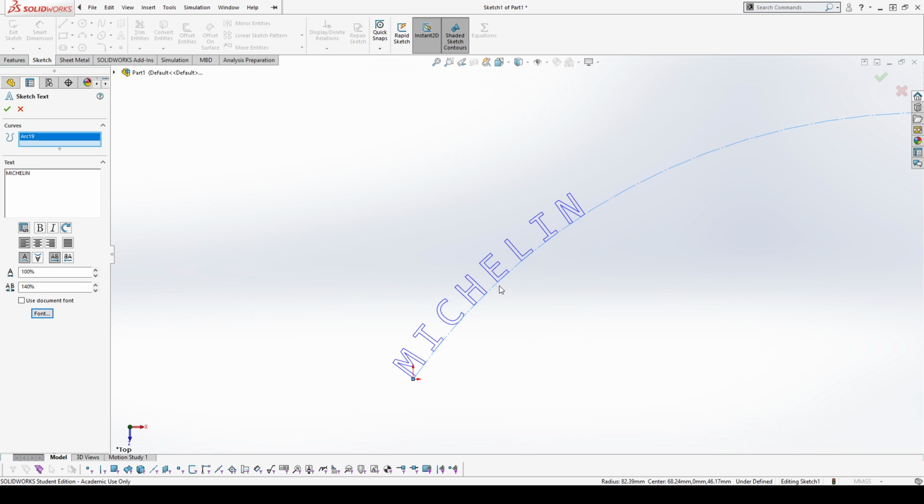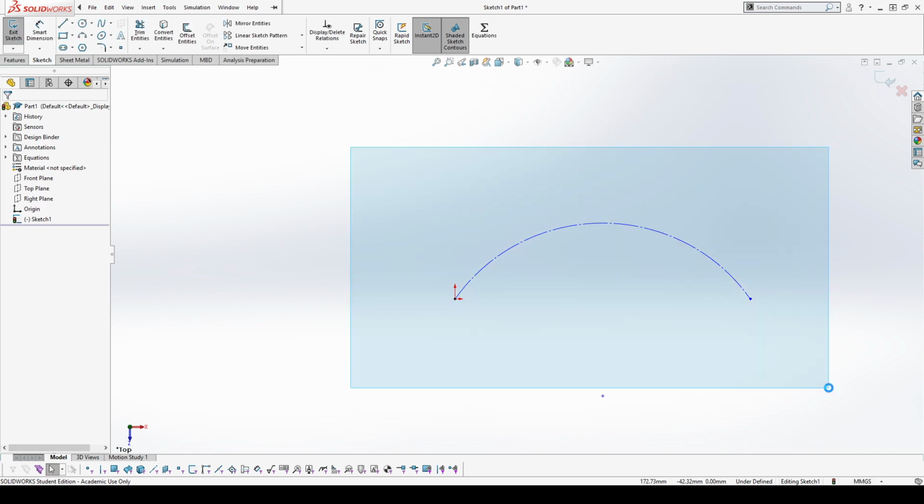Fairly rarely used, I'd say. A lot of the parts that you're going to be sending out for machining, for example, aren't going to have text on them. It's very hard to machine text. But if you're modeling parts for 3D printing, it's a good one. Just adding in something like, hey, this part was made for Viking Motorsports. You'll see that on a lot of commercial parts. It's a good idea to mark your parts, or part number embossing, for example, if you have a particular part number assigned to it. That's your options there.